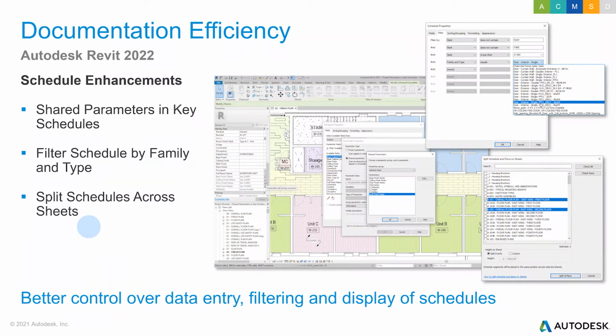If we look at doors as an example, we can do a door schedule and we can schedule out the heights, the widths, the colors and materials and so forth. But doors might have maybe a hardware package that's attached to it. And those hardware packages can come in a variety of different combinations. A key schedule is essentially one of those packages that define what kind of hardware can be attached to it, and that acts as a key reference inside that door schedule.